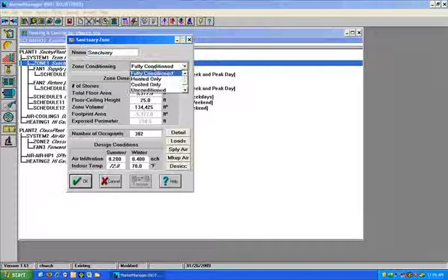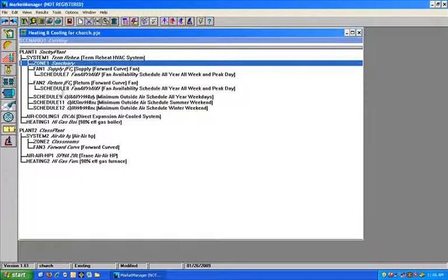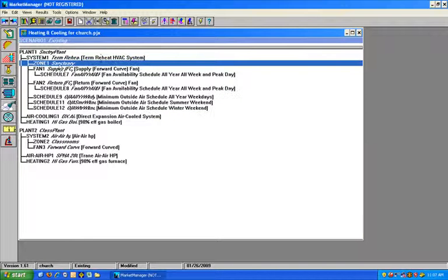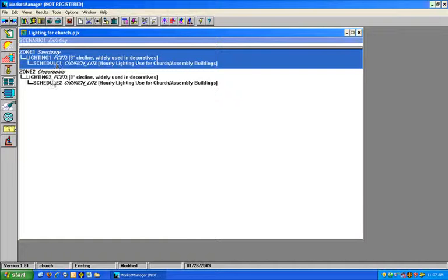First off, zone conditioning. If you want to have an outdoor zone, let's say some outdoor lighting, outdoor pumps, maybe you have an outdoor pool, then you can make this an exterior zone. And if you do that, then you probably don't want it under a system because there's no air handling happening there, right? So then you could just cut it, not delete it. You cut that zone, and then the zone's still going to be around.